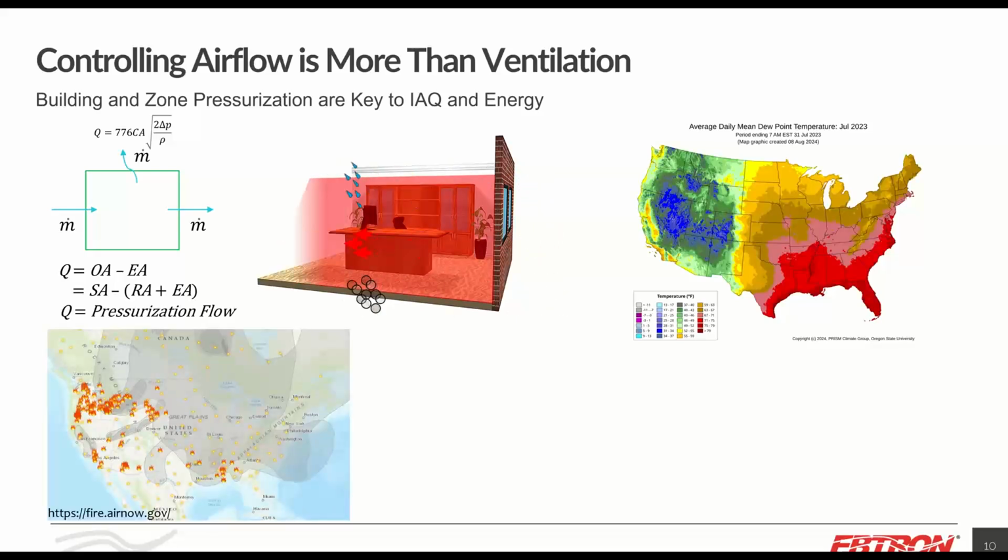And another thing we have these days is wildfire smoke. It travels quite far. There'll be wildfires up in central Canada or western Canada, the mountains, that would travel down the East Coast, and we've all experienced it in recent times. What's happening in the smoke is you've got VOCs and particulate matter, and it's best that you filter those things out in the building. A lot of people will say, well, let's shut off the outside air damper completely, and that's the wrong approach. And Guideline 44, which was released, addresses that as well.